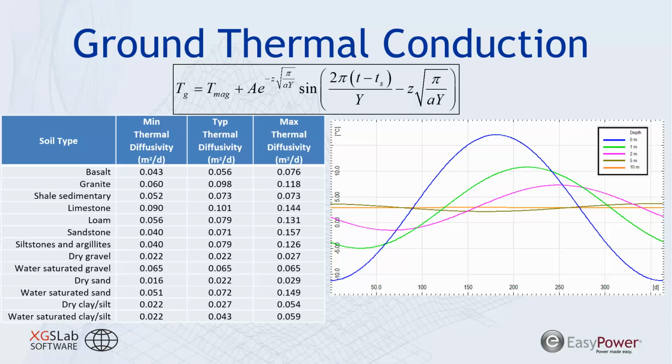Now what we're able to do is take the mean annual air temperature and translate that into a mean annual ground temperature. And we can use that fluctuation that we saw annually and adjust it based off the depth of the soil and its thermal diffusivity, and come up with an approximate or calculated value for the soil's temperature, and use that in calculating its respective soil resistivity at any point of the year.